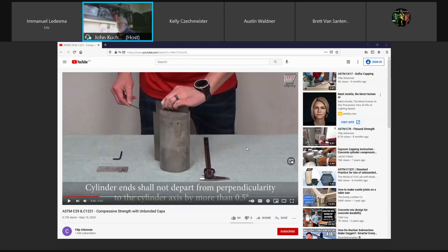of the vertical. This is the important part, because when you load the machine, that knuckle that you saw, remember there was a little schematic of the platen and the compression machine? There was like a socket, like a knee socket. Well, the top platen of the compression machine can swivel a little bit. So if these cylinders are off just a wee bit, it'll conform to it, okay? That's what that knuckle in the platen was, like a knee socket. But again, it's only got a certain amount of curvature or movement. So if this was way out to lunch, you would have to cut these cylinders and get them back to the proper dimensions. So let's work on the video caption here and then we'll take it from there.